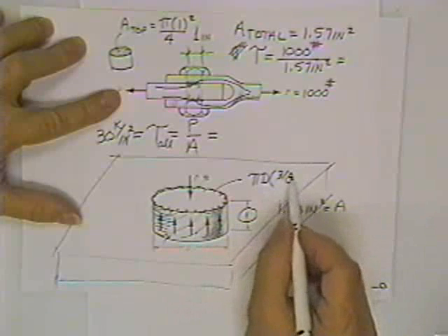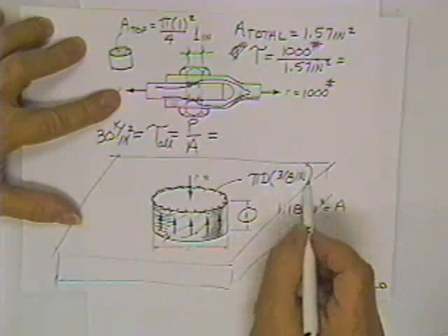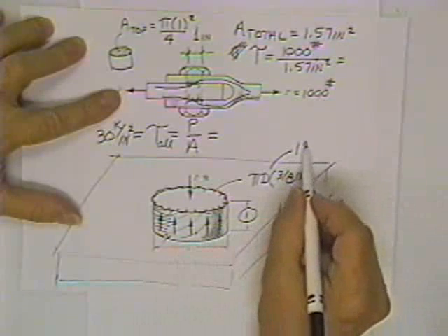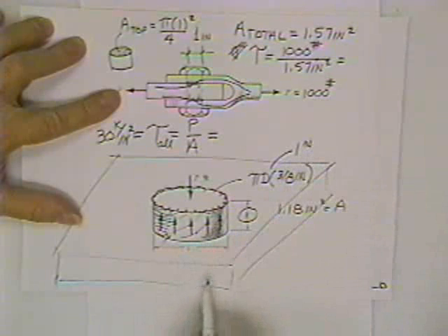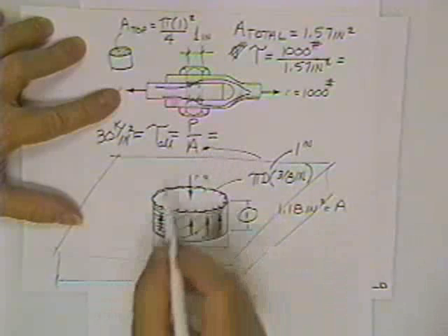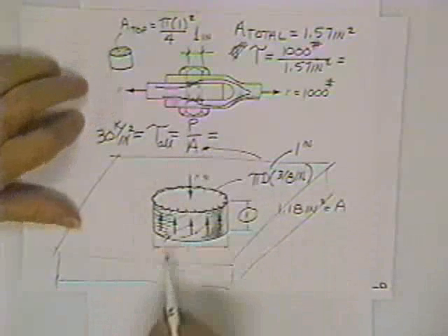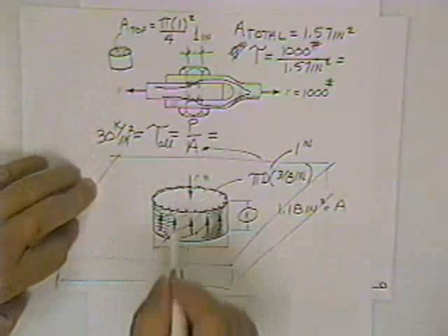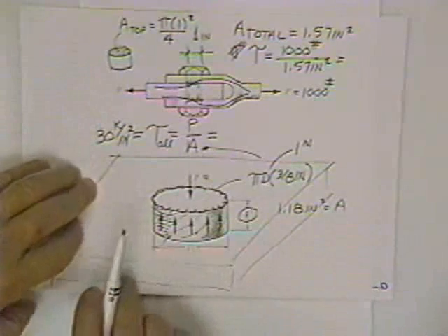In this case, the plate was 3/8 of an inch thick, and the diameter was given as 1 inch, and you have your area, pi times 1 times 3/8. You stick that number right in here. Then you could solve for how hard it is to poke a hole in a piece of structural steel so that you could bolt it on the job.